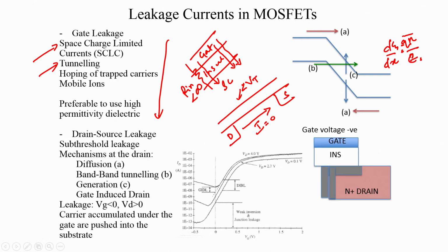Okay. Or in other words, if you remember the switch for sending a signal from A to B, when the switch is open, we would like the resistance of this MOSFET or this switch to be ideally infinite. Okay. So, if VDS is 0 and if VGS is 0, there should be no current in the MOSFET, there is nothing driving any current mechanism.